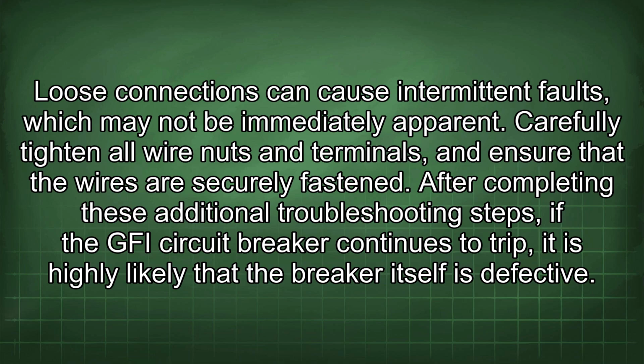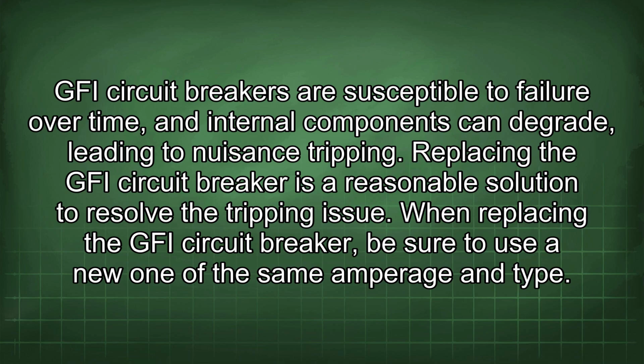After completing these additional troubleshooting steps, if the GFI circuit breaker continues to trip, it is highly likely that the breaker itself is defective. GFI circuit breakers are susceptible to failure over time, and internal components can degrade, leading to nuisance tripping. Replacing the GFI circuit breaker is a reasonable solution to resolve the tripping issue.